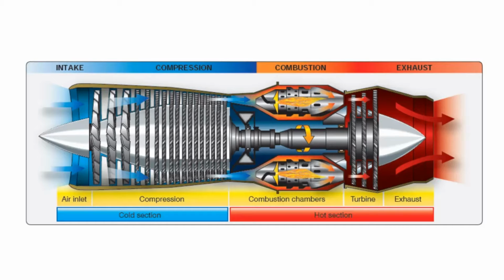Blades are the most abused part in the gas turbine engine and hence are prone to failures very easily, and so their design is the most vital part of the success of any gas turbine engine's design and operation. Blades are used in various forms: compressor blades, turbine blades, guide vanes which are the stator vanes, and impellers which are axial compressors. You can see here, these are the blades.